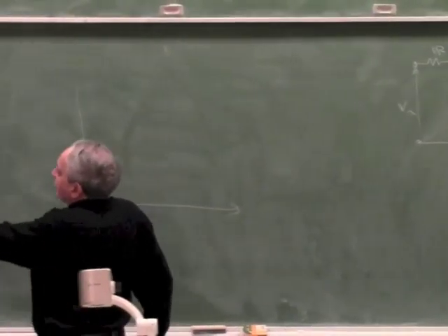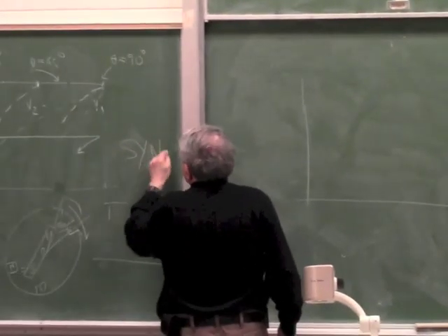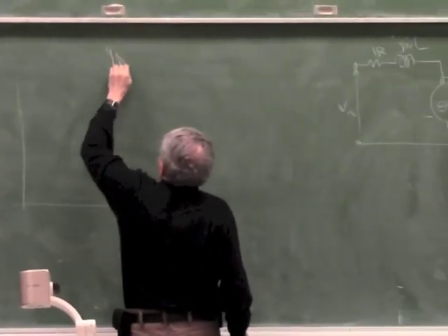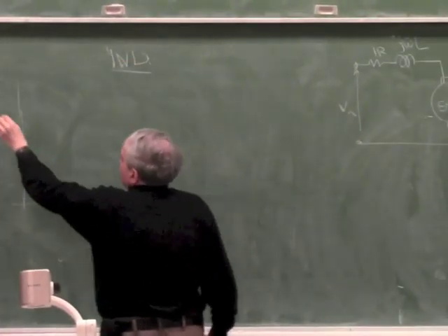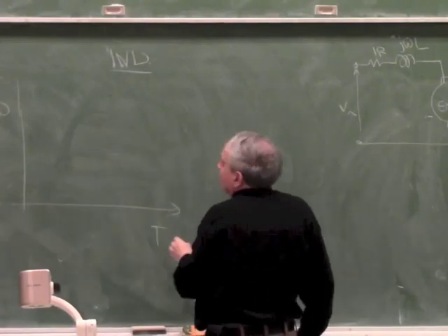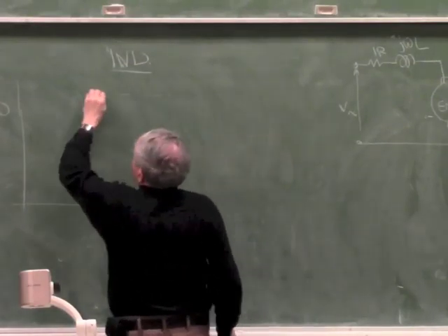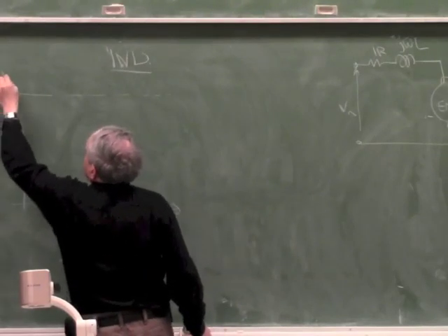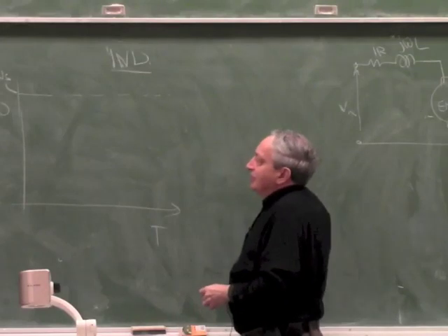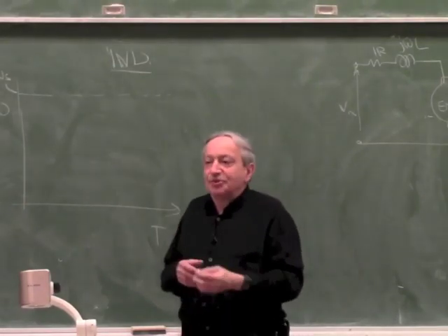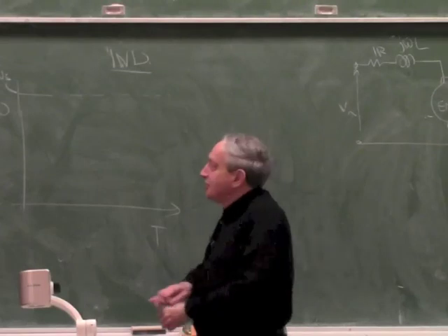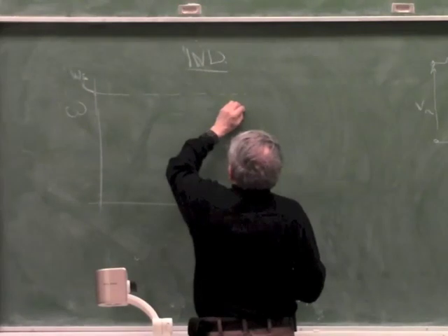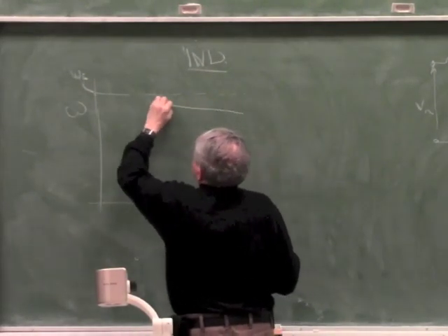So this was synchronous motor. Now this is induction motor. So if this is omega and this is torque, we said if this point was omega s, meaning the synchronous speed, the way it will work, it has to have slip to generate an induced current in the armature. So at zero torque, it may have near zero slip, and it has a small slip which I'm drawing exaggerated.